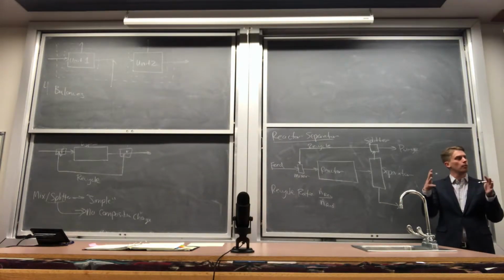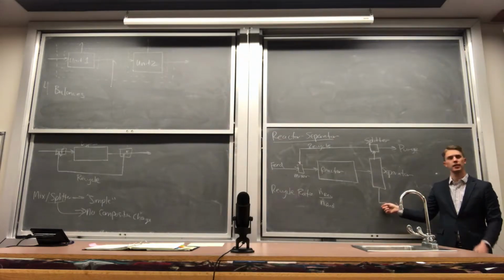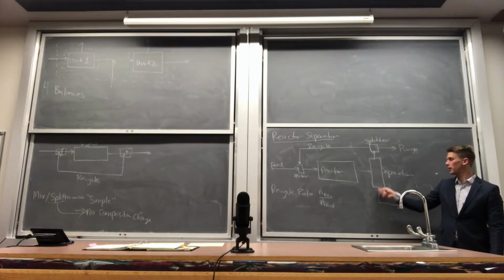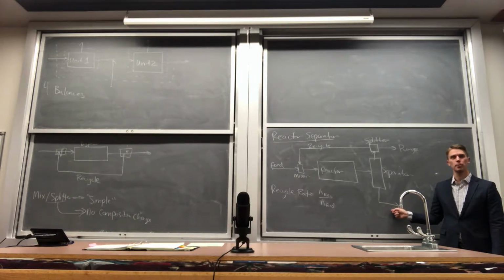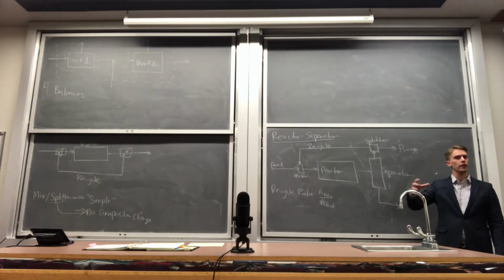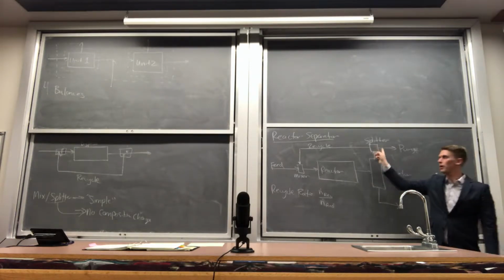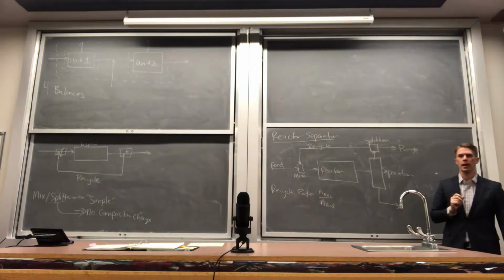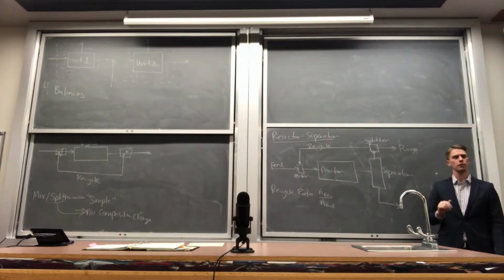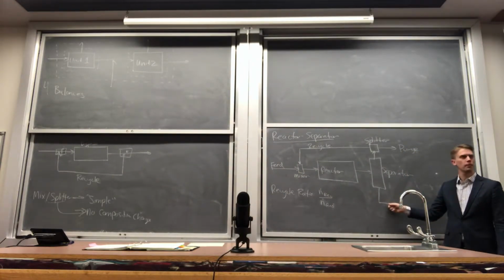Now a bigger, more complex molecule is easier to condense into a liquid phase or crystallize out into a solid, which means it's typically going to be coming out of the bottom of any unit operation separator, whereas the cheap, readily available, simple molecules are more likely to be in the gas phase, which is why they would come out of the top and be recycled back around. But that's the general rule. It's not always going to be the case. But in general, the goal is to make bigger, heavier, complex molecules at a rate that is cheaper and more efficient than anyone else can make bigger, heavier molecules.